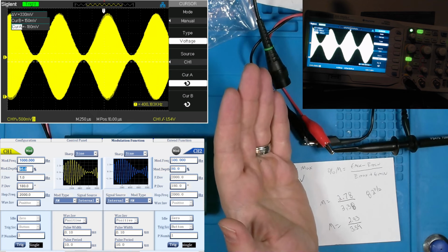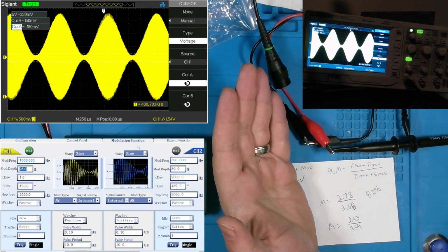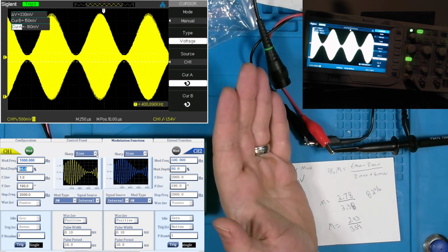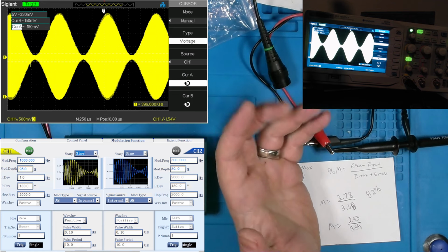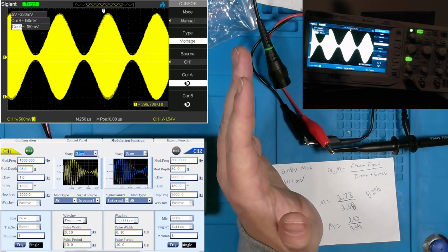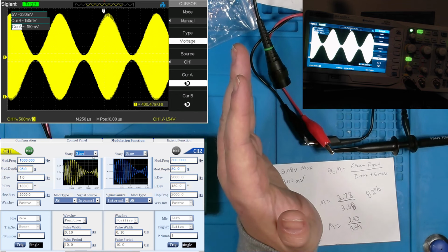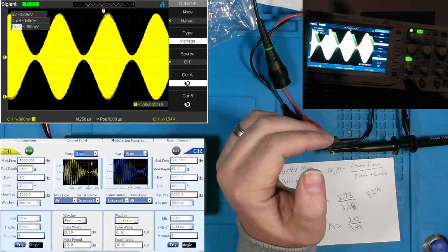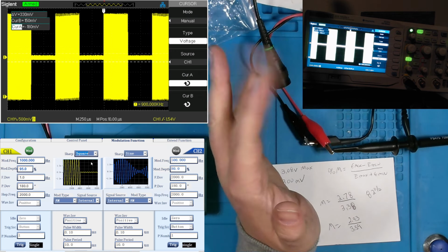Well, when it comes to modulation, you could have modulated output, but the actual waveform might not look correct. As a matter of fact, in a lot of amplifiers, when transistors in the power amplification section start going bad, you'll start to get very weird waveforms. So let me change it to what a square wave 1 kHz waveform looks like.